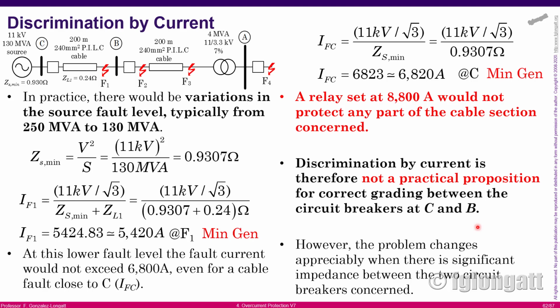But if you are at the peak level and you have a very high load, there are more synchronous generators connected to the grid. There are more machines in parallel, and the total equivalent impedance is decreased, creating big short circuit levels. At substation, at transmission, distribution level, sometimes you have 2 or 3 transformers working in parallel. When the load is low, you have only 2 transformers, but if the load increases, you can have 3 transformers in parallel, decreasing the impedance, increasing the short circuits.